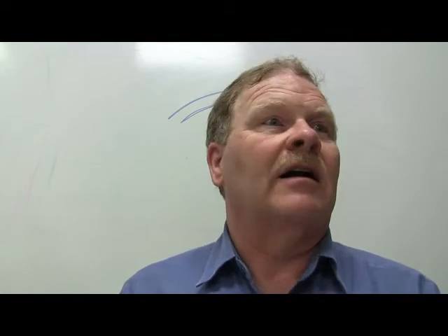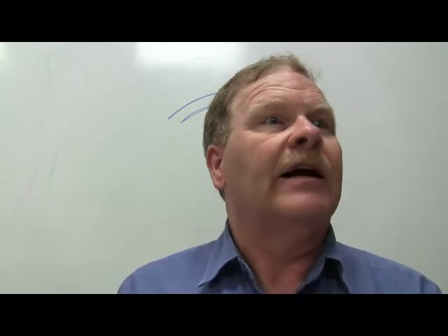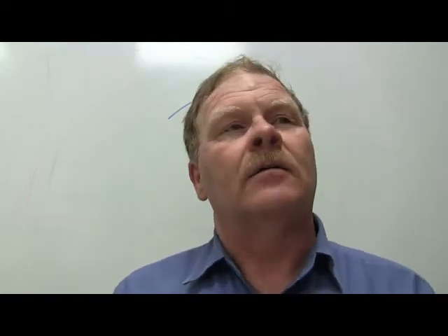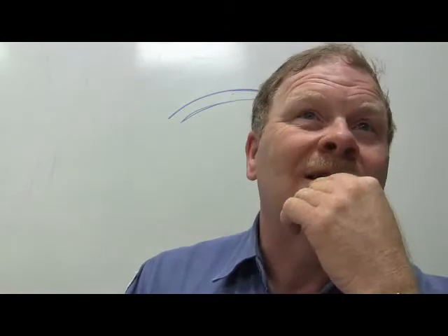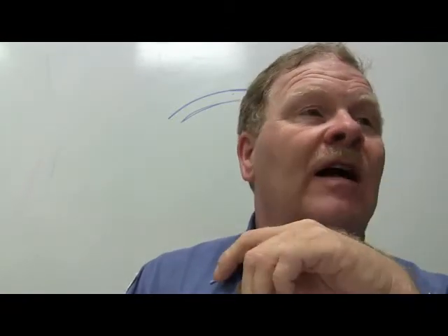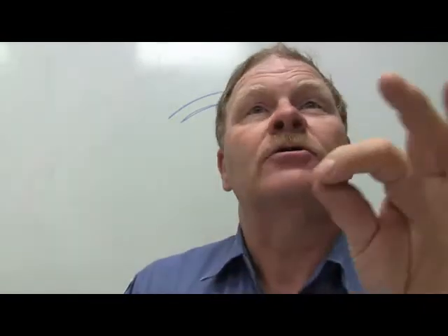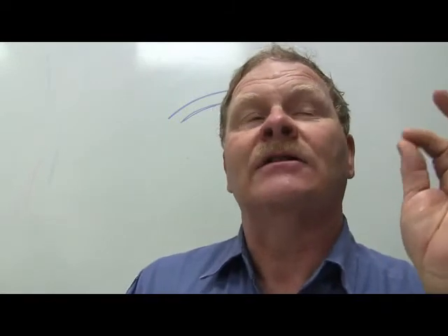So I'm digging around down there behind where the fog light ought to be, looking for it. I didn't find anything down there. The book told me it's down there behind it. It doesn't give me a picture, it just shows me words. So I said, well, that's a bunch of hogwash. I don't see it down here, so I'm going to follow the hoses. Here's a vacuum hose going from there into the engine compartment, into the passenger compartment.